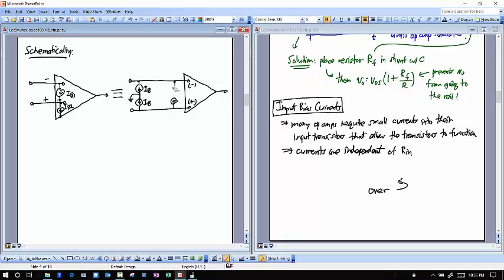Let me draw these a little further to the left. So two other current sources that model the differences between those. And this is called the offset current, IOS. So this one coming down from the top will be IOS. This one at the bottom will be minus IOS over 2. So this is sort of a difference value of current through that.